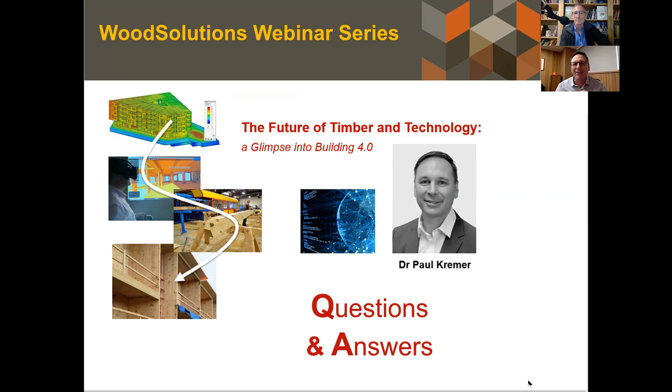My good friend Alan's online from, I think, Brazil today. I'm not sure whether he's in lockdown or not, but he asks, how do you deal with clients wanting to show the timber structure outside of the building with no cladding? You don't. It's too big a risk, unless you can come up with a timber cladding which sits on top of a membrane that is watertight. Then it's effectively a false cladding. I think that's the only way, and it would be really the way to go forward.